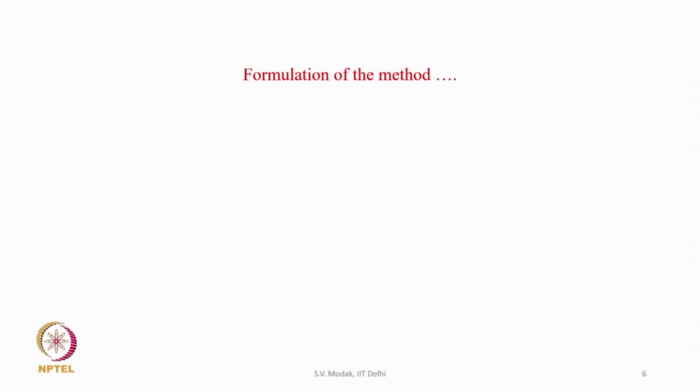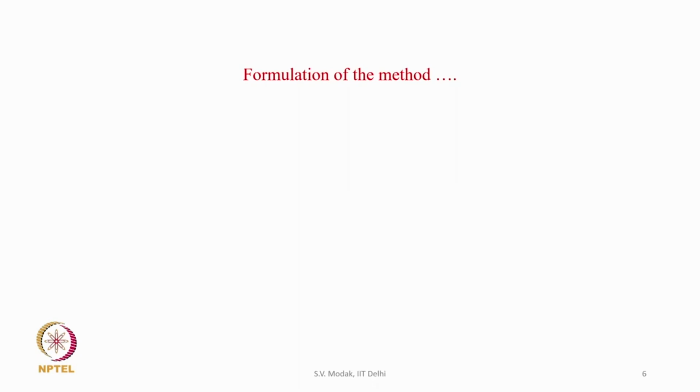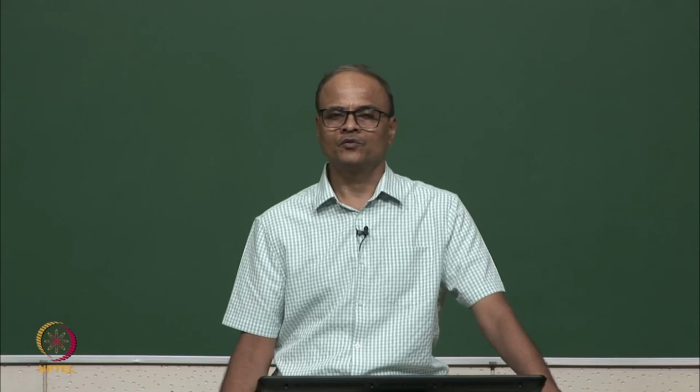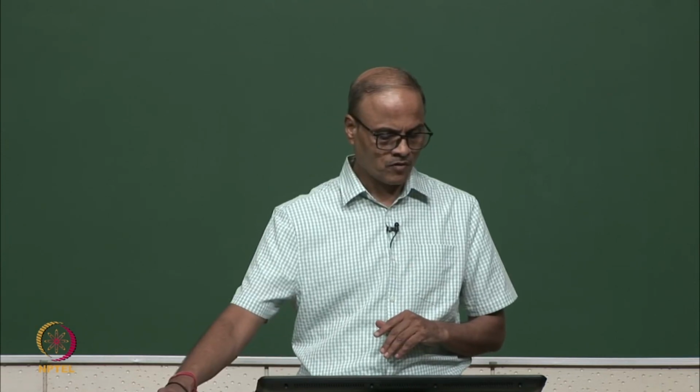Now, to solve this free vibration of the modified structure, we transform the displacement vector of the modified structure to the modal space of the unmodified structure. Earlier we studied the modal transformation, where we use the eigenvectors to go from physical space to modal space, but in this case we are going to use the eigenvectors of the unmodified structure. Let us do that transformation.